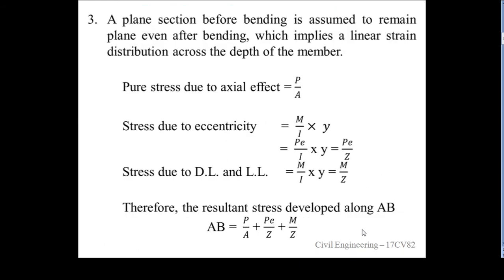Then the third assumption is that a plane section before bending is assumed to remain plane even after bending. This is a well-known assumption made in concrete also, that a plane section remains plane, which implies a linear strain distribution across the depth of the member. These are the assumptions made before developing an equation for stress.